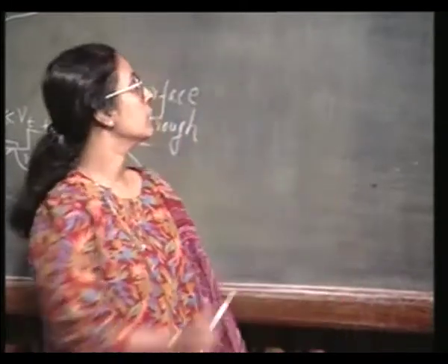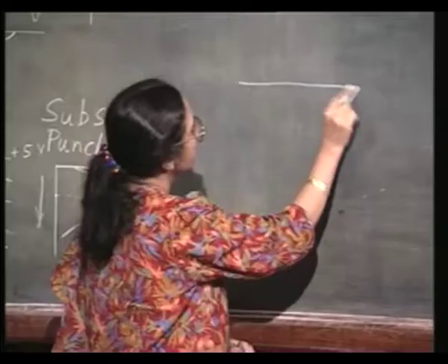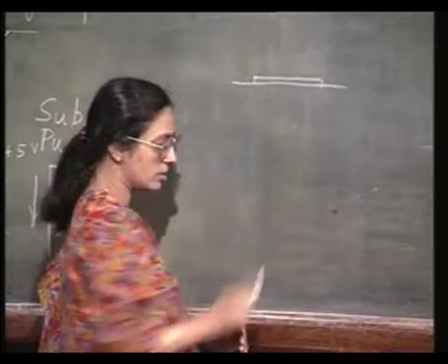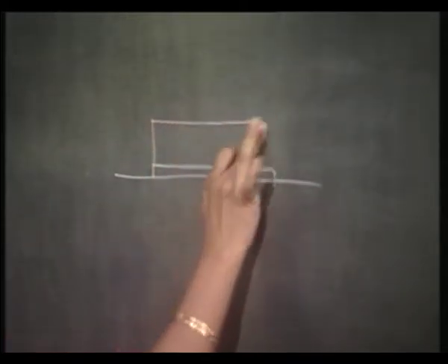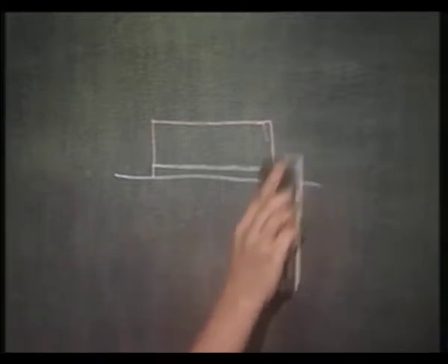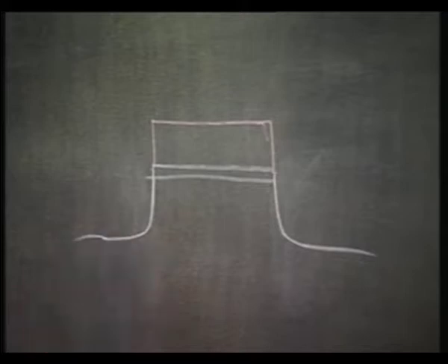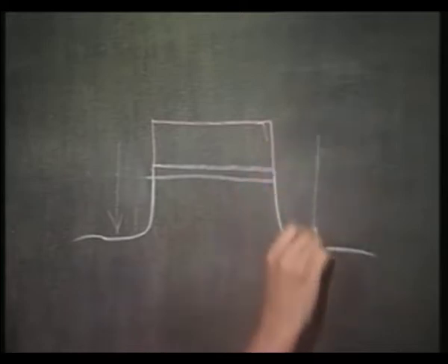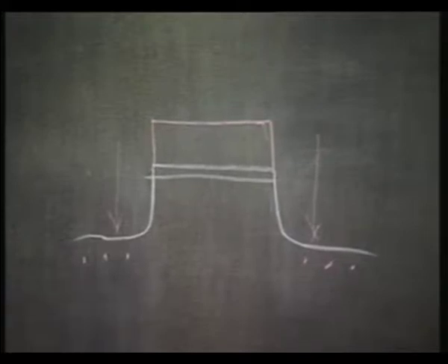Now you know that the field oxidation is done by LOCOS. So, before doing LOCOS, what did you do? Remember, this was your active transistor region which is protected by this thin pad oxide and on top of that silicon nitride, right. And then if you want to have a recessed structure, you have etched it out, right, and then you are going to grow the thick field oxide. Now, before growing this thick field oxide, you do an implantation here. And then you carry out the oxidation.